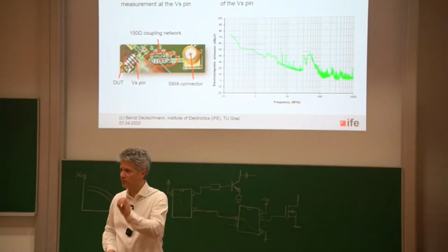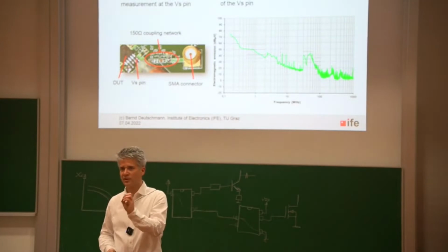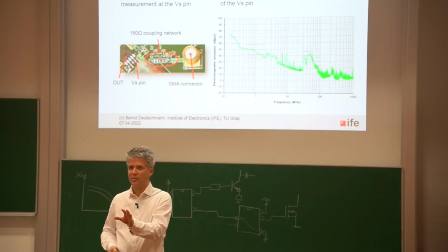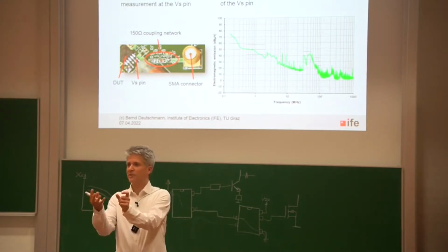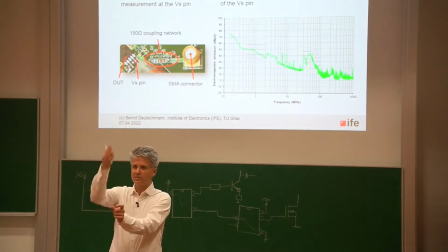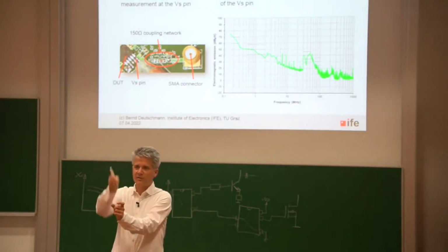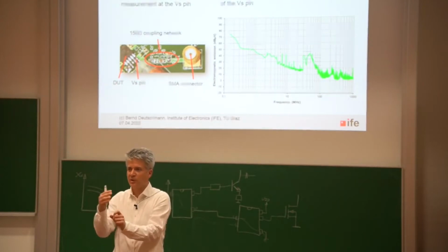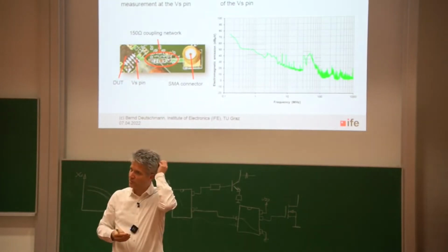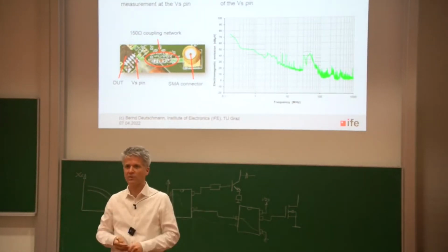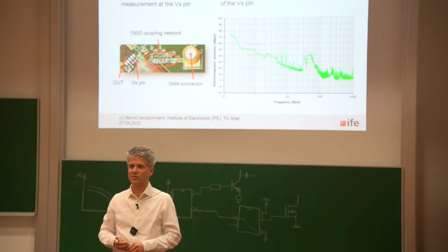As I said, we have to measure at each frequency position at least 3 times the operation cycle of the IC. If you're violating this rule, then it can happen that we are at a certain frequency position and suddenly the microcontroller wakes up and produces more electromagnetic emission. So this can happen, that there are certain frequency ranges where we have increased electromagnetic emission. But let's suppose we are measuring in a correct way. We are waiting at each frequency position as long as needed.